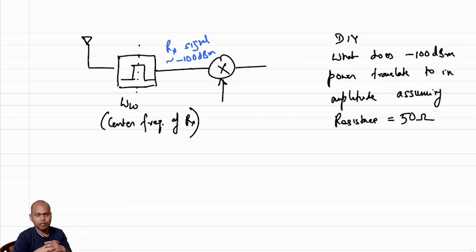You cannot have an extremely small input, then the ADC will always give out 0 0 0 0. You might say that I can always take this signal and amplify it. Sure, I can do that. In principle, I can keep amplifying any signal, even if it's minus 1000 dBm. But we all know that's not the case.